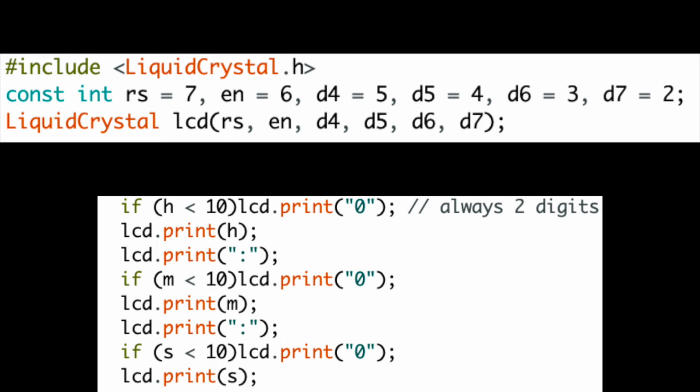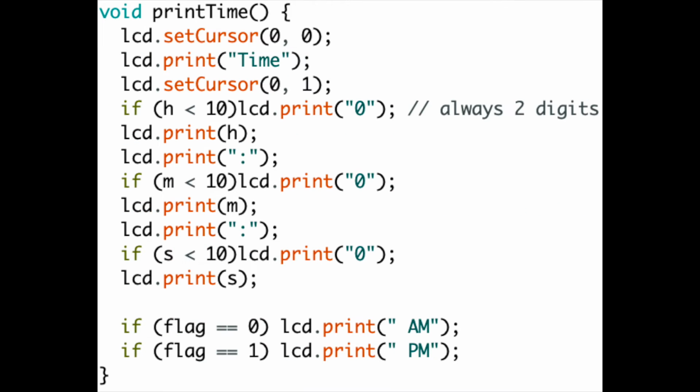Writing LCD instructions into the Arduino program has to begin with an inclusion of the LCD Arduino library, followed by a connection assignment of each LCD and Arduino pin. It can then be freely used to write characters based on the digital LCD pins that have been wired to the Arduino. Elsewhere, the creation of most of these characters comes from variables.